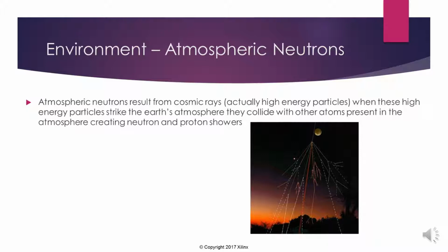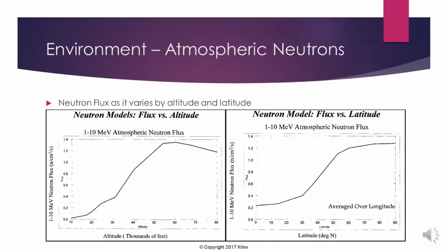Now if you're doing a space design, then there's much more to consider than this, and we'll mention it briefly later on. There are things like single event latch-up, single event burnout, single event gate rupture, which we don't really see in a terrestrial environment at all, because they're not that high energy, but we do need to consider the bit flip. What's interesting about the bit flip is it varies with both altitude and latitude. In some cases we can use the device manufacturer's own design tools to determine if we have an issue, because we can calculate the failure rate.